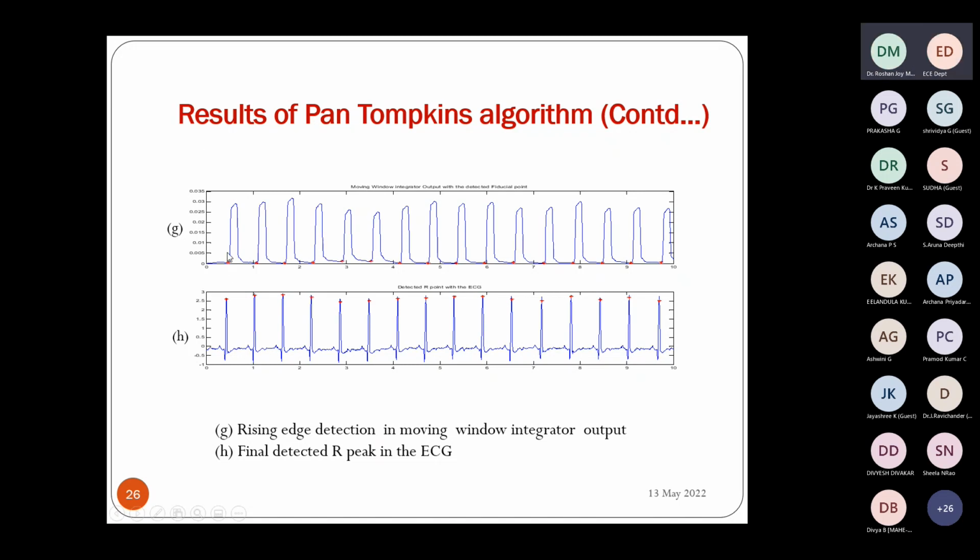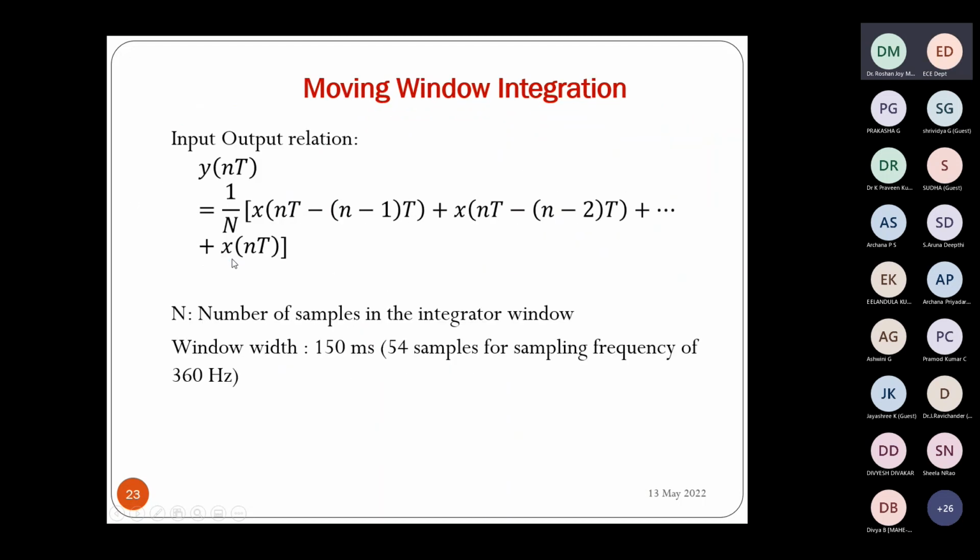We put a for loop, and inside that loop an if condition: if the value is lesser than a particular threshold and the next sample is also a low value, then it is not the point. The present value should be low and the next value higher, and that point is the rising edge. That has to be computed, and then you have to add all the group delay.